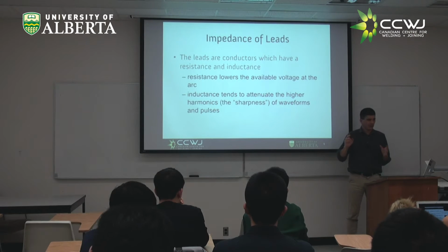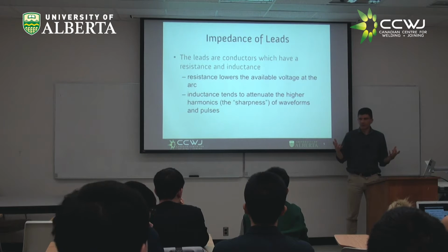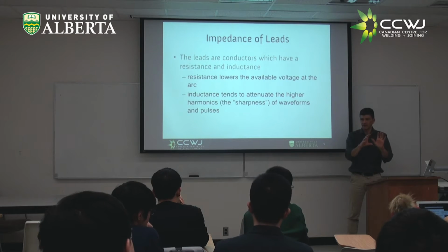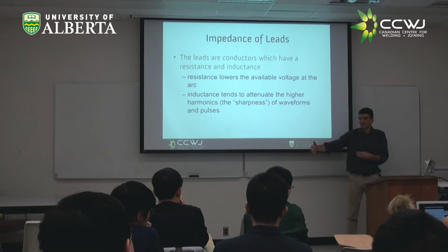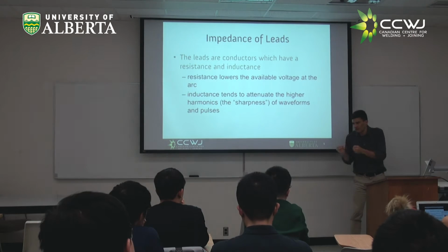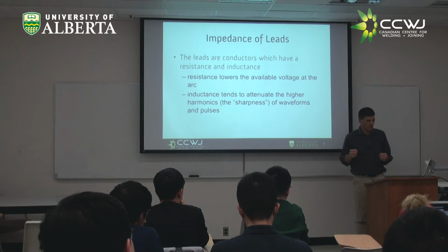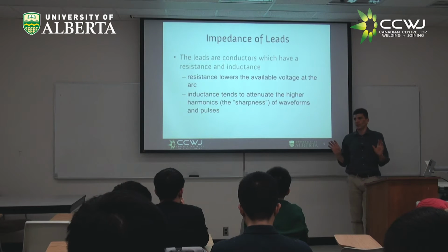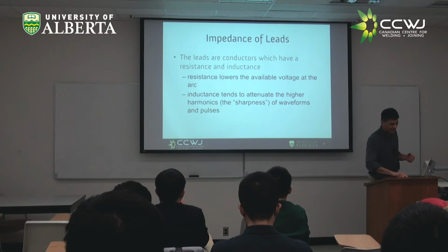For that reason, and I'm still waving my hand, when you want to use things like STT, which you all know very well, or any other type of pulsing, as we discussed last class, you want to have short leads. Because if you have big leads, you start to have more and more inductance, and that starts opposing your machine trying to change the current. All right. So enough of waving hands for now. I want to give you a few numbers so you have a sense. All right? Okay, for the leads.